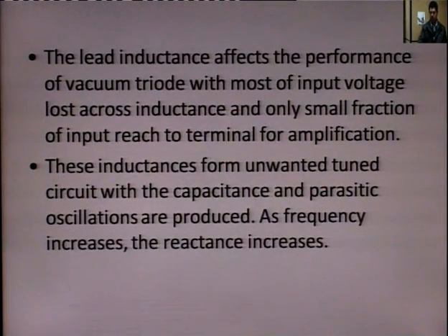So, at microwave frequency, this inductance increases. Due to this increase in inductance, most of the input voltage will be lost across the inductance, and only a small fraction of the input reaches the terminal for amplification. And even this inductance, together with the parasitic capacitance or interelectrode capacitance, can cause unwanted oscillations that will definitely create noise or reduce the gain of vacuum tubes at high frequencies.